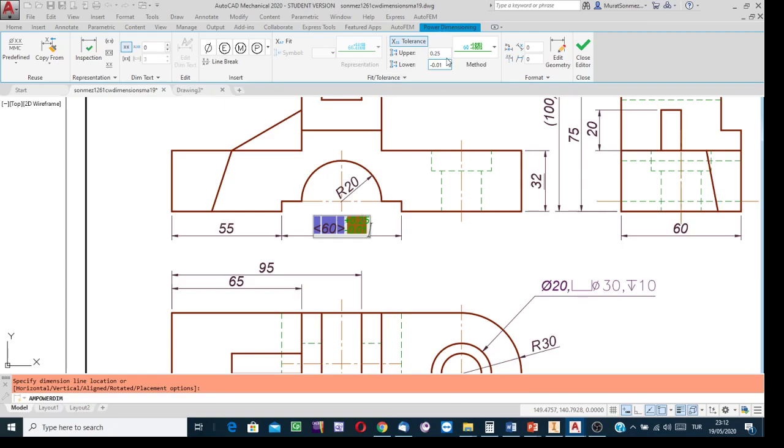If the deviation value for the other started from hundreds, say that this is also a space holder, then I need to show this dimension not as an integer but as a decimal number. In AutoCAD, for the other non-functional dimensions, we checked that deviations almost all start from tenths. So during the dimensioning configuration stage, we selected 0 precision. But here I need to show this dimension not as an integer but as a decimal number.